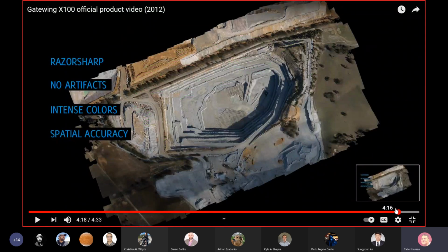In this picture you see the product, and this is an orthophoto. I think in my class you learned about orthophoto. It's a photo from which we have removed all the relief displacement. It has the advantage of a map because it has only one scale, and also the advantage of a photo because it is rich in color information, where you can see where is the mine, where are the trees. Color information is nice to have, not just like a map that has some names.